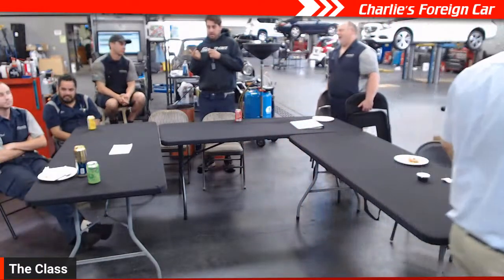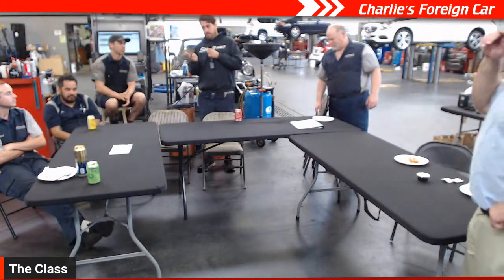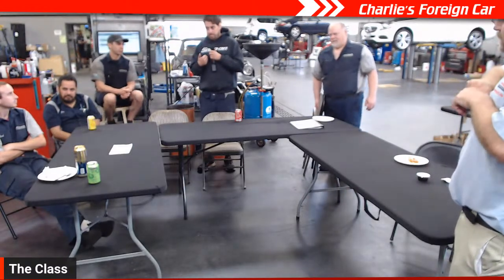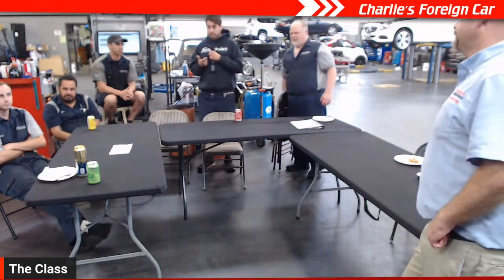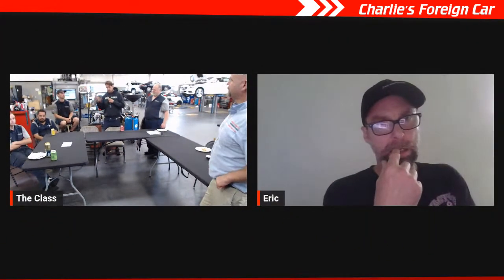Everything got proved out. PCM got proved out that it's okay. We tried to prove out we had mechanical flow, but we don't. So we have a mechanical issue there because we already proved out the component is good by swapping it and putting a new one in. VVT obviously got switched out, so we have a new component there. And we just verified again that the PCM is working. So it goes back to mechanical or flow to the VVT to control it. Yeah, it's either mechanical restriction or mechanical defect.